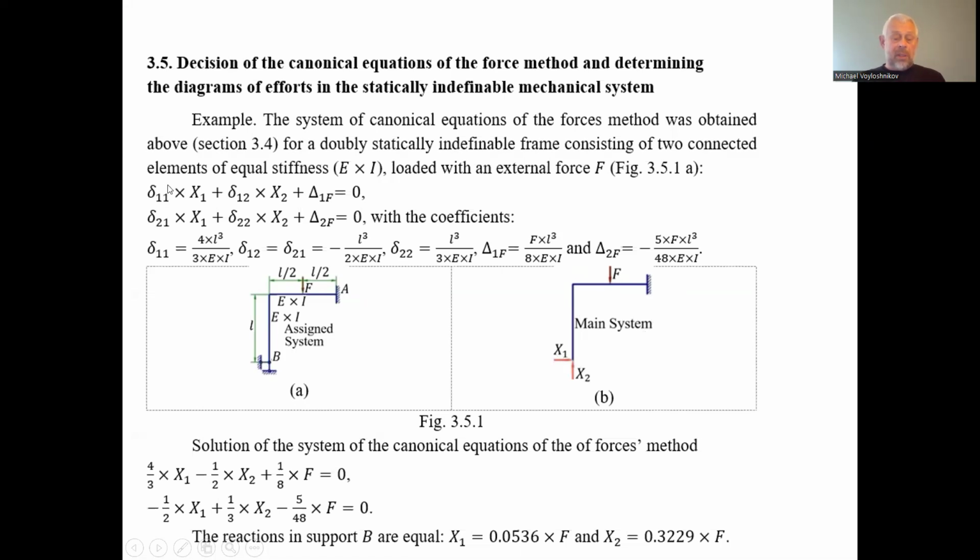We use the canonical equations. It could be the canonical equations of the force method, as we substitute the cutoff links by the forces. And in the assumptions of the force method, when we apply the forces, we have to find the magnitudes of forces x1 and x2 which satisfy zero displacement of the point B with the cutout supporting links in the direction.